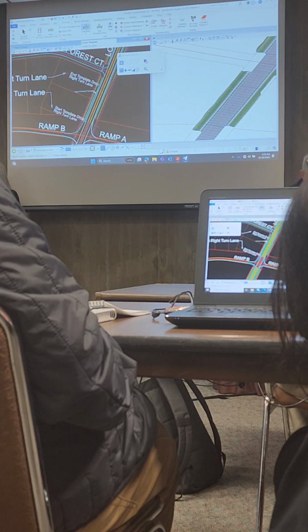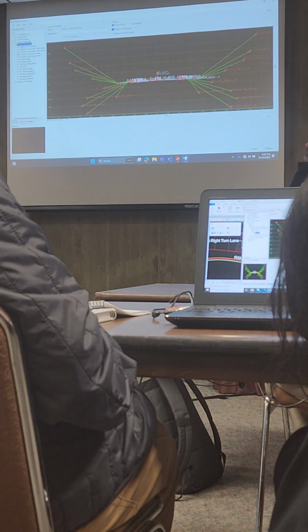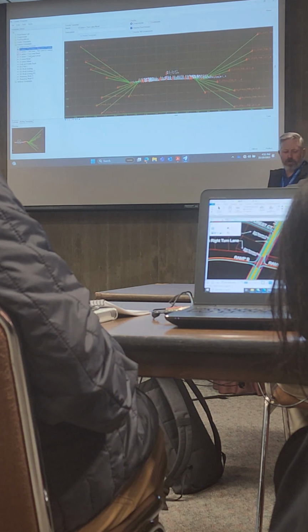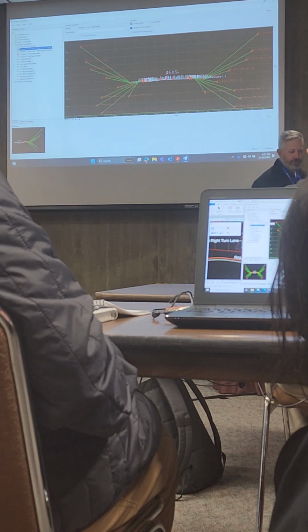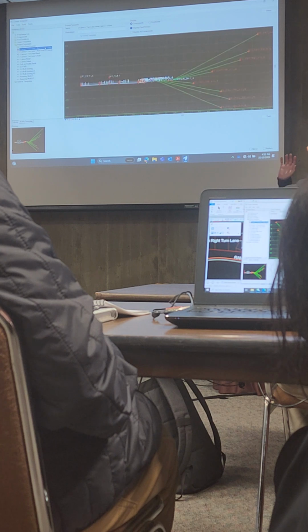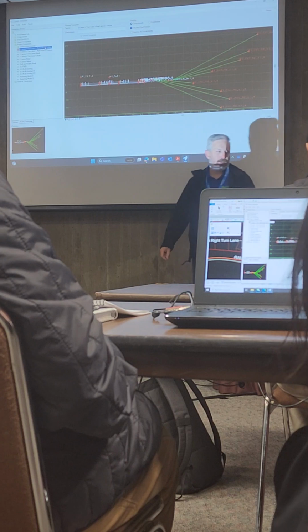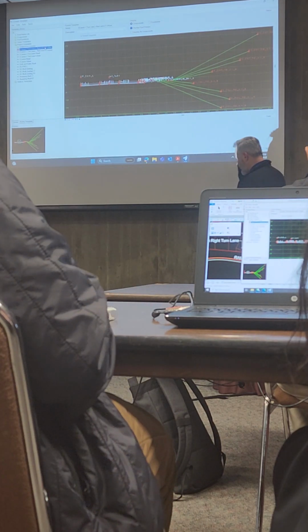We're going to go look in this library. Because what Scott's given us under the project templates folder, so I'm under the project templates folder, let me stretch my window out so you can see, we're looking for this 2-lane plus turn lane, auxiliary lane, left urban. I'm going to double click and it changes my view. So I double clicked on that template and it's now setting this to my active view, showing me this template.